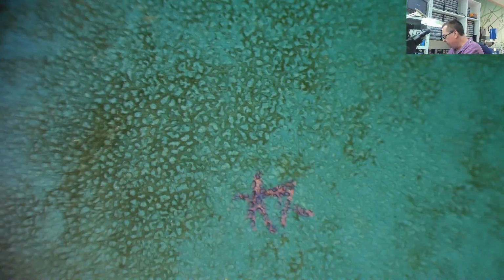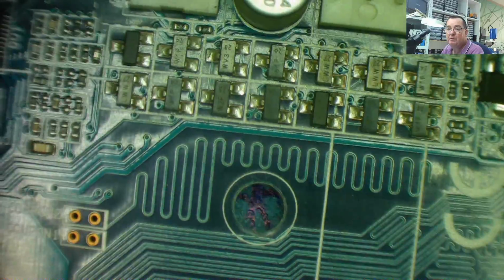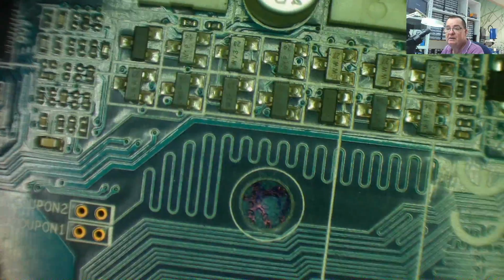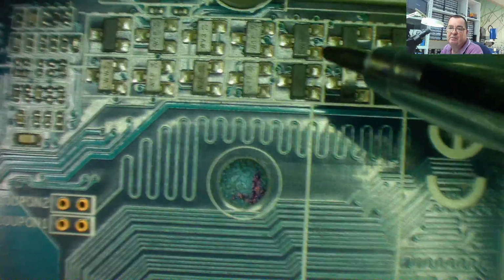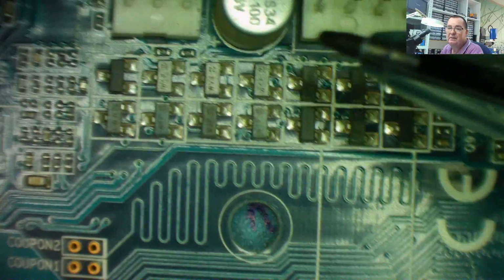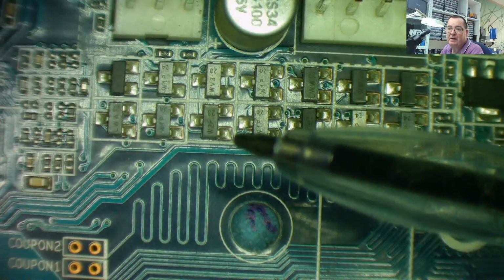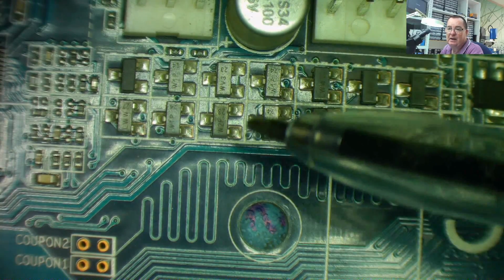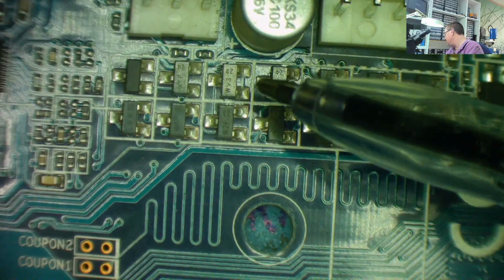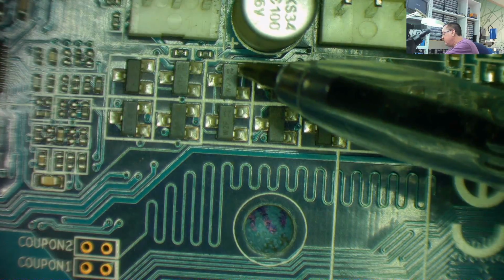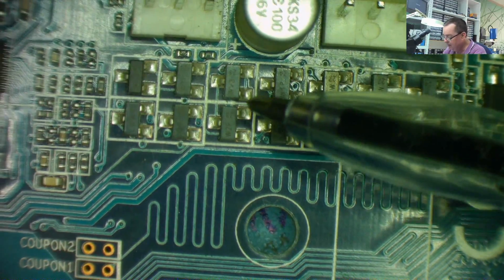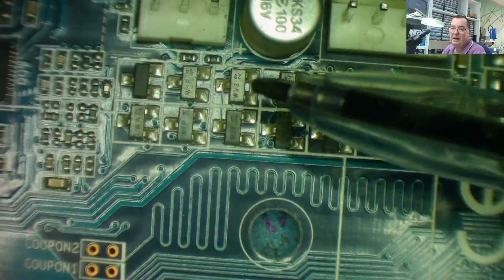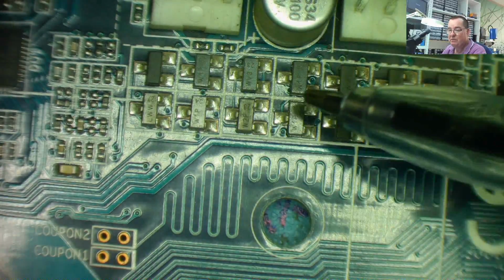Let's have a look at another board. This is a motherboard, a scrap one. Again, there's lots of devices down here. These could be transistors, they could be diodes, they could even be something else. So often with these type of devices, in fact this WV3, I'm sure that is actually a diode. In fact, I'll even tell you what that one is. It's a BAT54, because I came across some of these on a faulty board on a video recently. BAT54. And these come in diode networks.